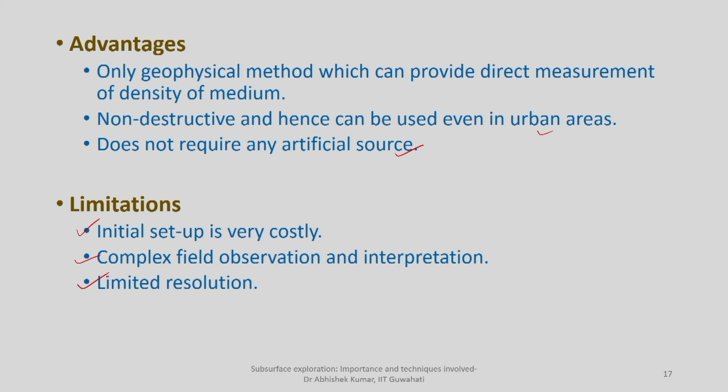Then limited resolution: depending upon the geology of the site, the depth up to which you can get an idea about interpretation will restrict your resolution with respect to depth. As you go for larger and larger areas, you can get more idea about tectonics, cavities, mineral deposits, geology variation, and so on. Now, we discussed advantages, limitations, applications, and also the different corrections to apply to field observation, so that the final value can be used for interpretation. Now, let us see some numerical problems.